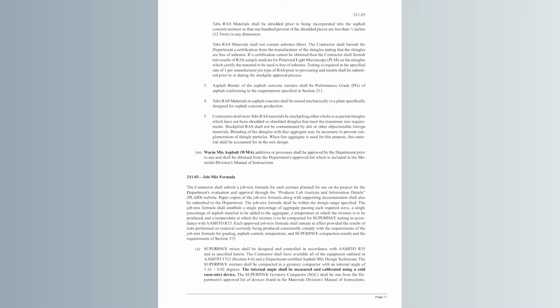Letter A talks about that your Superpave mixes need to be in accordance with AASHTO R35, and you need to have all of the equipment that's outlined in that, as well as in AASHTO T312. And every company needs to have an asphalt mix design technician on staff.